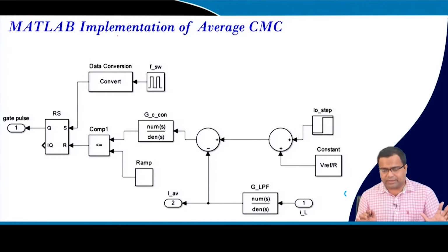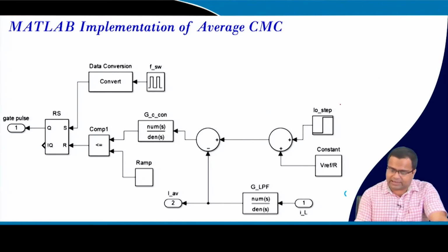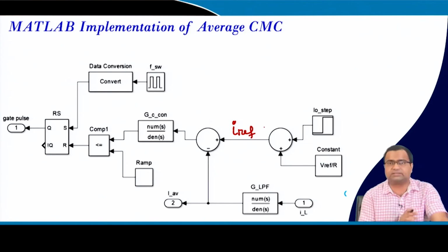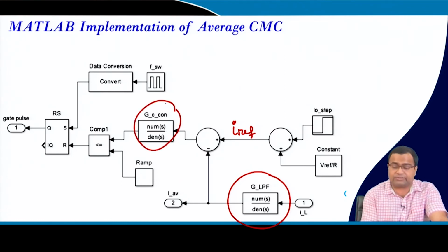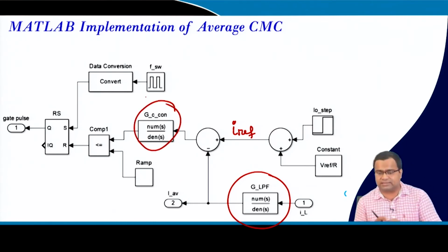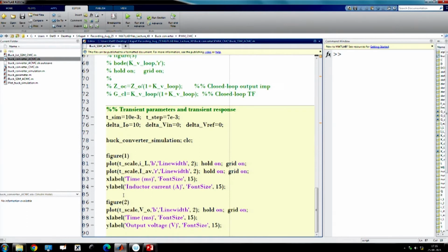So, one way is to set just a reference current, with no outer loop as we have discussed now, and then either you take a low bandwidth current sensor or you adjust the bandwidth here, and we want to see how it is going to track the current. Okay. So, let us go and check the simulation.